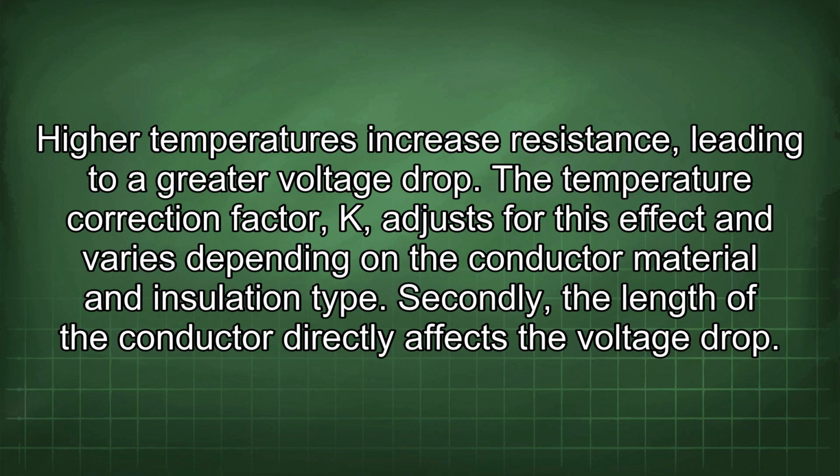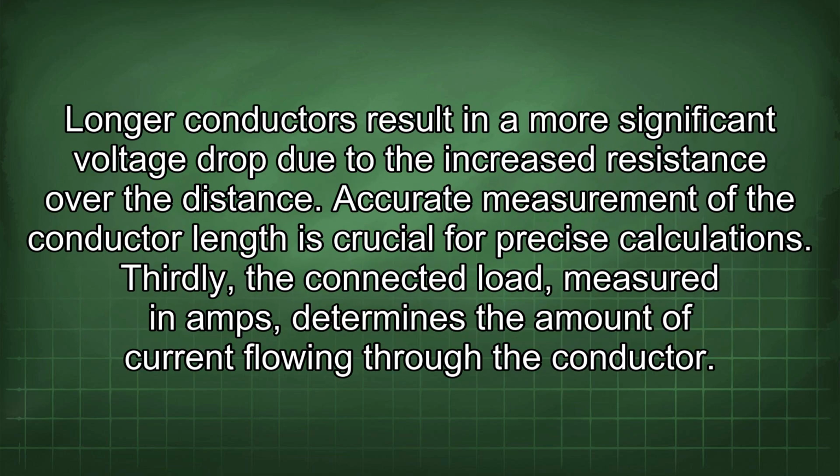Secondly, the length of the conductor directly affects the voltage drop. Longer conductors result in a more significant voltage drop due to the increased resistance over the distance. Accurate measurement of the conductor length is crucial for precise calculations.